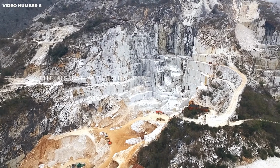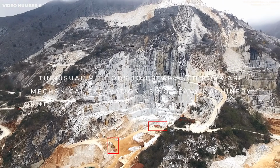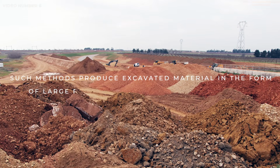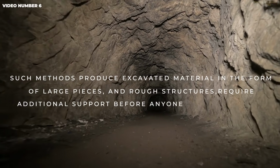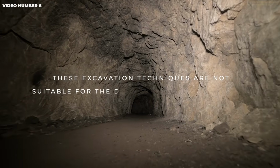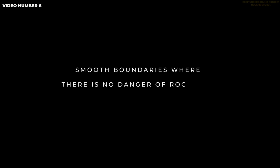The usual methods to break such rock are mechanical excavation using heavy machinery or the drill and blast method using explosives. Such methods produce excavated material in the form of large pieces. The rough structures require additional support before anyone can enter them. These excavation techniques are not suitable for the deep underground concept, which requires small-sized particles that can be removed with ventilators, fans, or pumps, and smooth boundaries where there is no danger of rockfall.